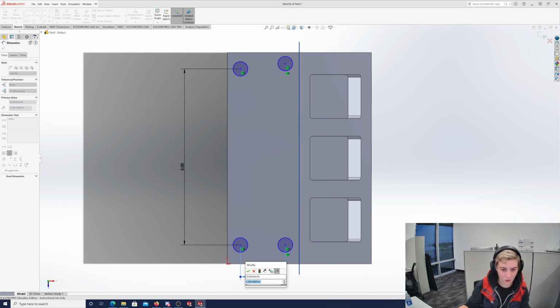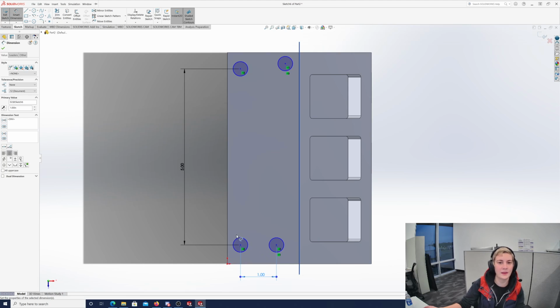So I mirrored them from the front ones. Yeah, so you'll have to use reference geometry and create a plane in the middle of your part, and then you mirror them around that plane. Yeah, okay.